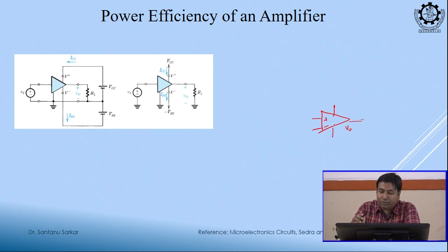So, generally we will be having two supply voltage pins. One is, suppose, we can have dual supply, means plus minus VDD, or we can have a single supply, that is VDD and ground. Clear? So, many of the 741 op-amp series you will be seeing that they are used in dual supplies, that means say plus 12 volt and minus 12 volt. Okay, that will be specified in the data sheet of this particular amplifier, that how much voltage is required.